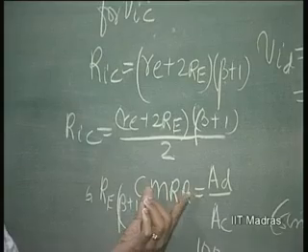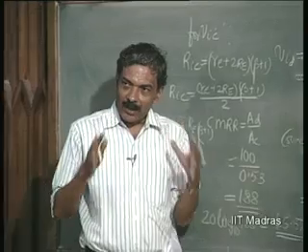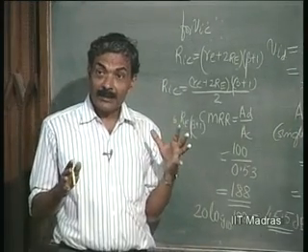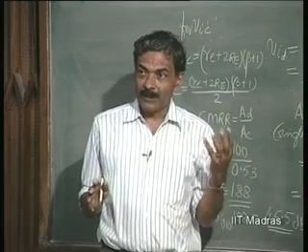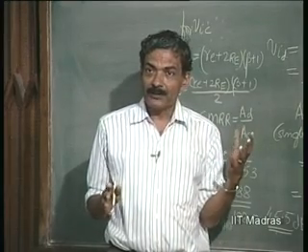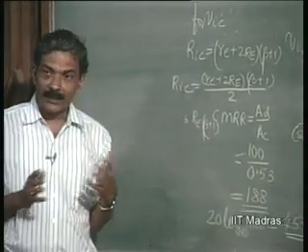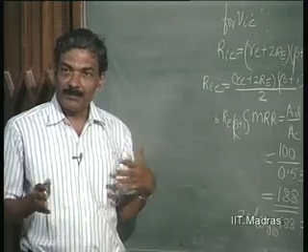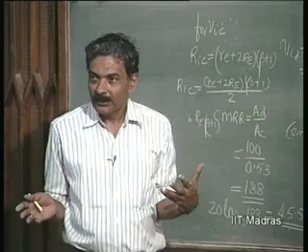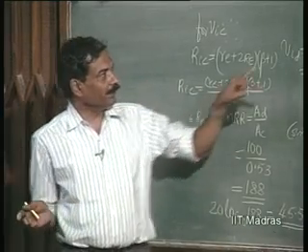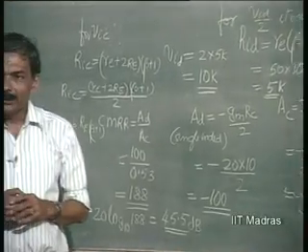This impedance divided by 2. Therefore, it has a common mode impedance component as well as differential mode impedance components. The differential mode impedance component, even though it might be low, the common mode impedance component should be very high. Strictly speaking, therefore, the common mode rejection ratio also is estimated by simply taking the ratio of the impedances. This RE divided by this impedance is going to give us the common mode rejection ratio.